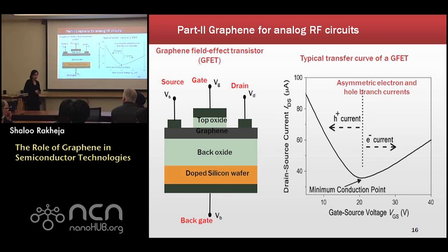Need to find an ideal layer thickness in your structures? Yes, we have. So this plot that you are showing us, I showed you over here, was computed for an ideal optimal number of layers for delay performance. And the thing is that as you keep on increasing more layers, the performance benefits don't scale with the number of layers. So we did all of that analysis. And you know the paper very well. And it turns out for those ideal ones? Yeah, for those ideal ones also they have these limitations. That's what I said, for ideal ones also a lot of limitations.